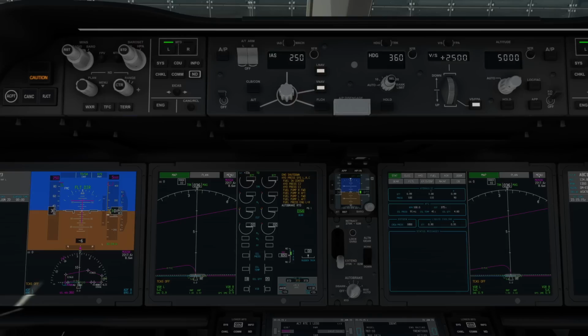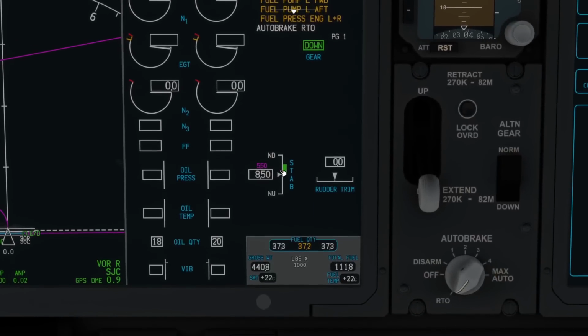And on the ECT screen in the middle now, you can see the stabilator trim, so we can use the elevator trim to move the elevator within this green box, which means when the aircraft accelerates on the runway, it will be in a position of equilibrium when it gets to the rotate speed, so it won't suddenly start moving around on us.